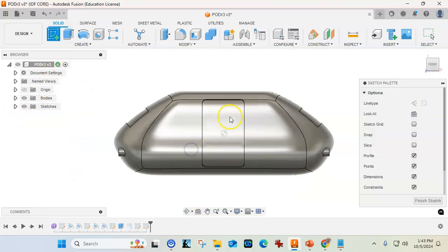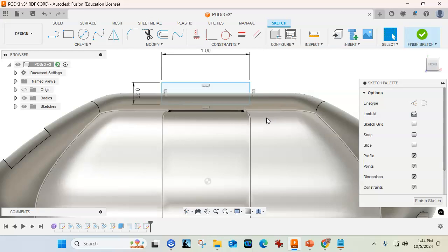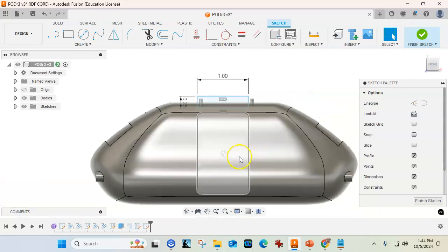So let's go into a sketch and we'll find some place to add a rectangle, and we'll make it 1 meter by 0.25, and then enter. And let's see, there's the origin. So if I were to go L on the keyboard and X on the keyboard, I would be able to find the midpoint, and then I would want to make that vertical.